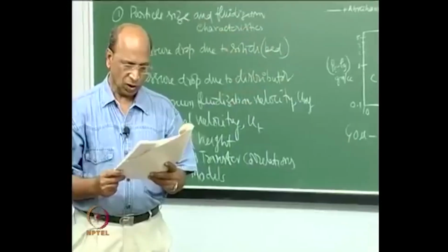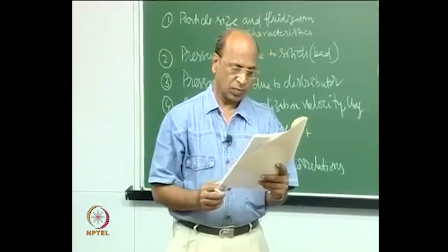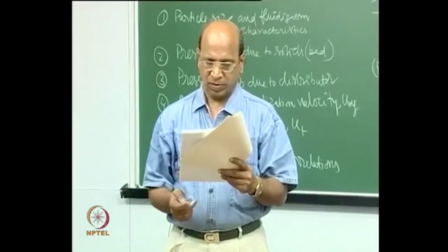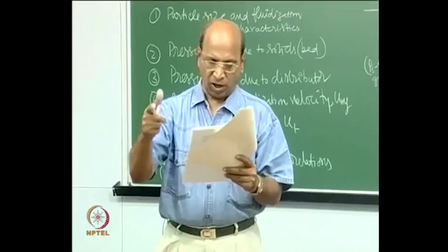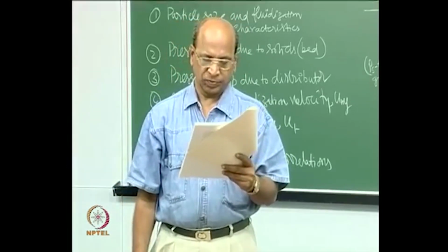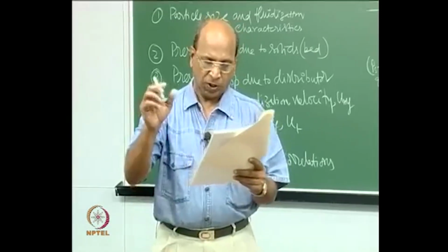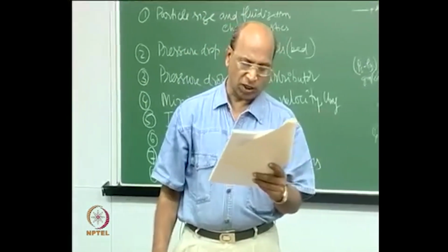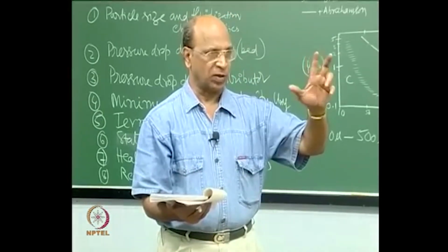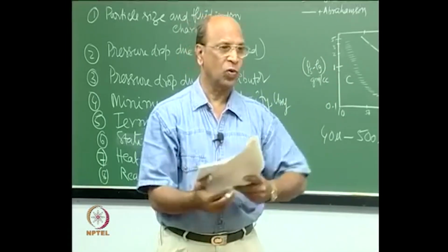Next one is group D. These particles are spoutable, large and dense. In fact, large and/or dense combinations. Deep beds of these solids are difficult to fluidize. Static bed, if you take 5 or 6 for example, L by D. Deep beds of these solids are difficult to fluidize.